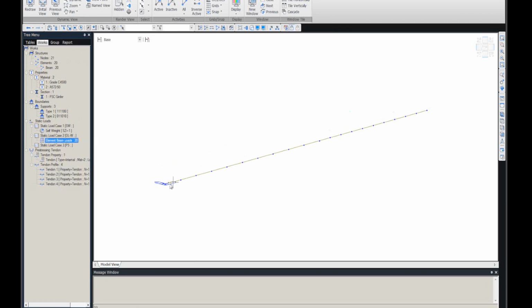Okay, you see that this model is only one beam, and this is the way that AASHTO actually recommends. AASHTO says that for the post-tension box girder, we can model it as a spine model, which means you are modeling the entire bridge as a single beam, and then you are just giving the sectional property of that beam to this structure, and then we can perform the analysis.